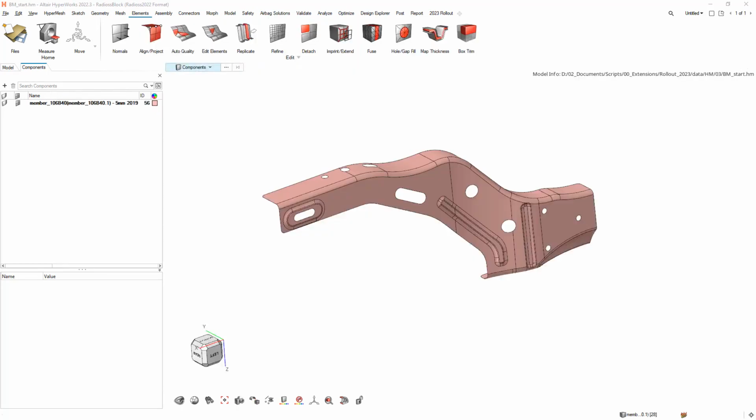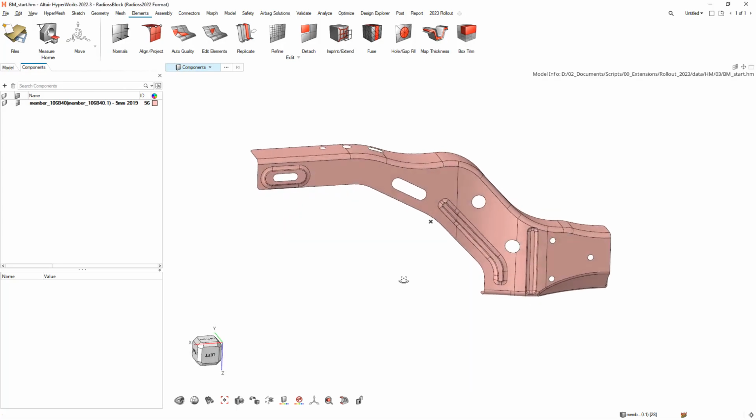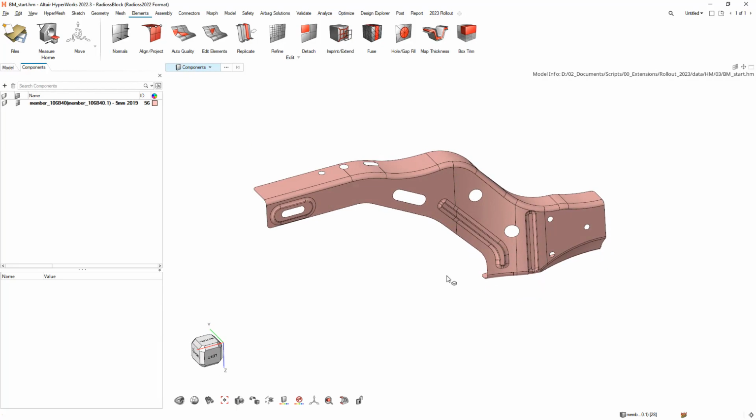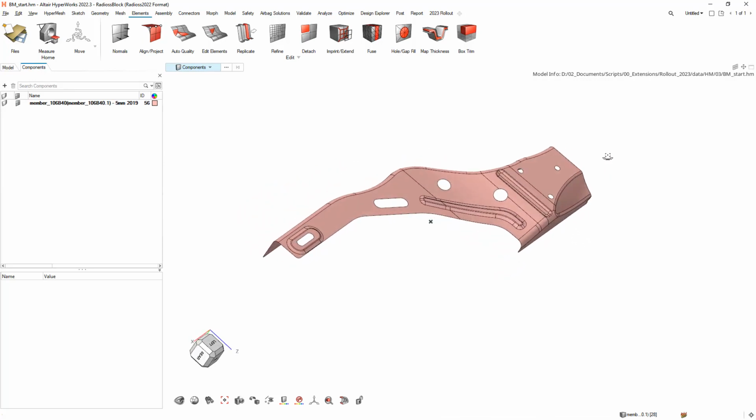So we've seen how powerful and flexible HyperMesh can be to give users full control over the detailed meshing and modeling with our tools. But to take advantage of these more efficiently, HyperMesh has also embedded these tools in batch processes that automate a lot of these common and repetitive tasks. So I'm going to start with the geometry on the screen. And some of the common things we've seen are things like suppressing edges, imprinting washers, those kind of things.